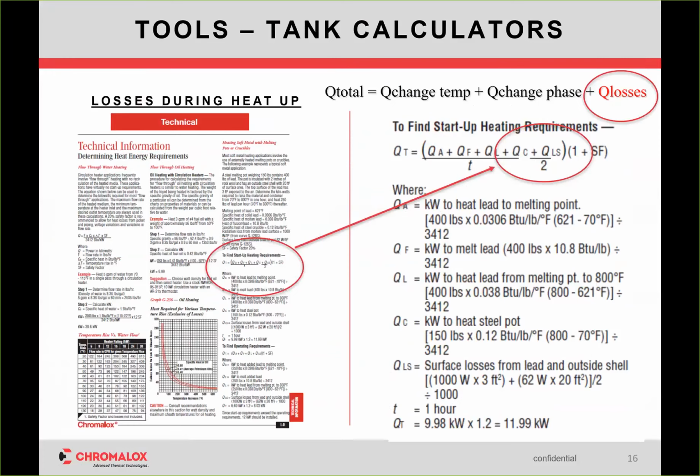But more importantly, in heat loss, when you're doing higher temperature tank heating applications, I mentioned before the gradient is exponential. So, as you get significantly hotter, there's a radiant effect. You're losing more to the environment without insulation. So you'll notice in all of our calculations, and in our calculator that you either have or will have at the end of the presentation, they divide the factor by 2. And why would they do that?